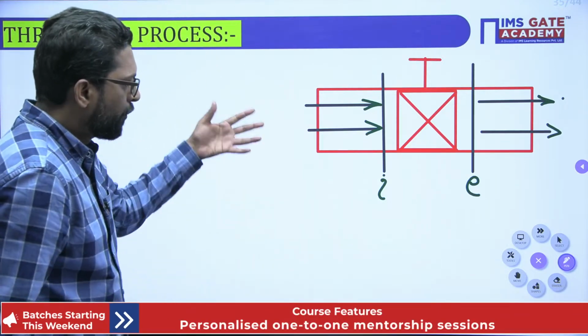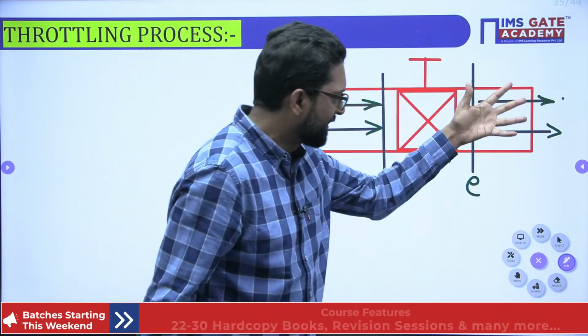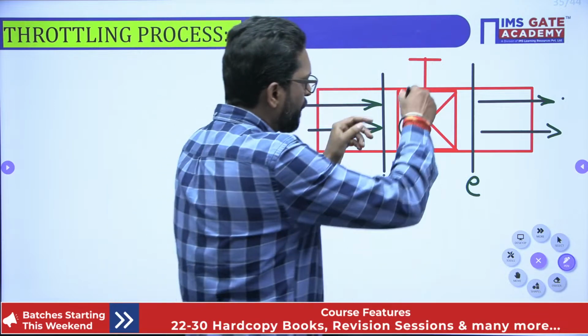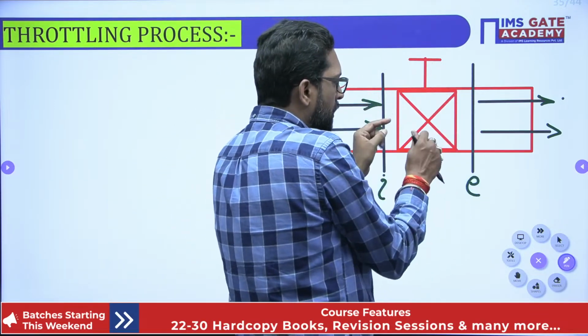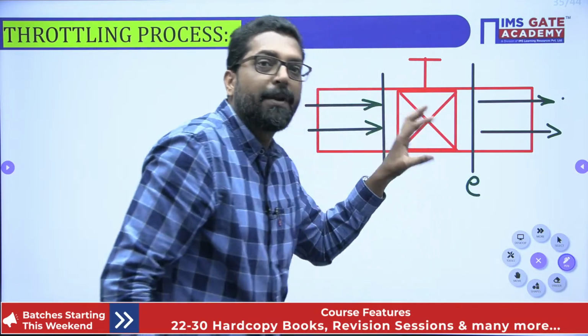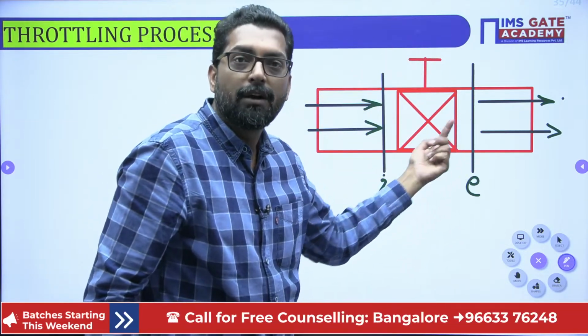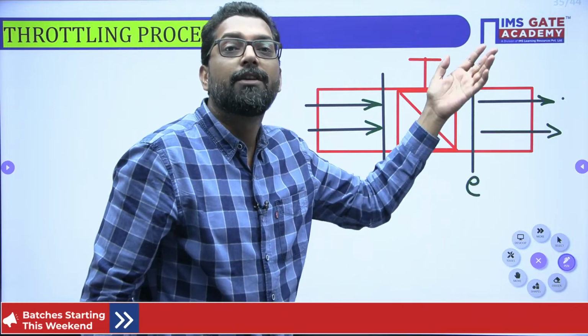Okay, so fluid is in here, fluid exits here, and this is our control volume. Now, if we reduce the passage, there must be a pressure reduction. If you reduce the passage, velocity increases, and when the velocity increases, the pressure will reduce.